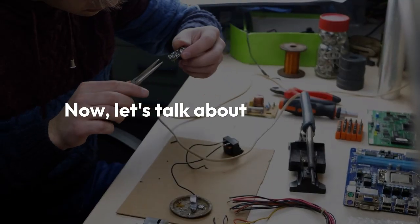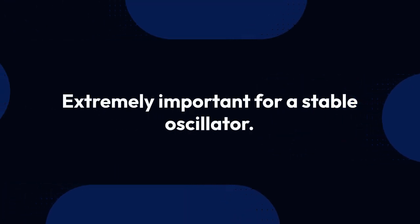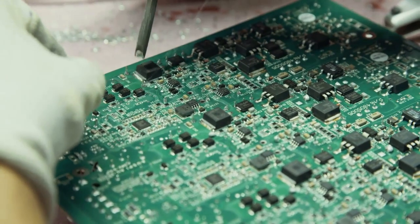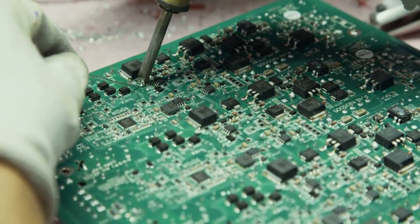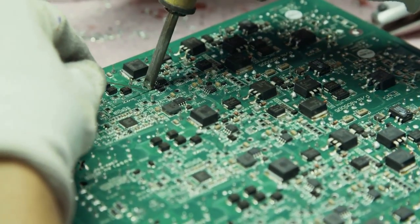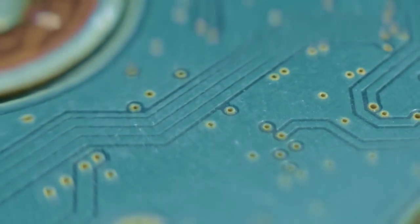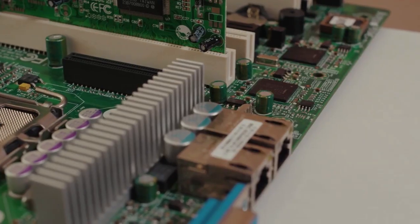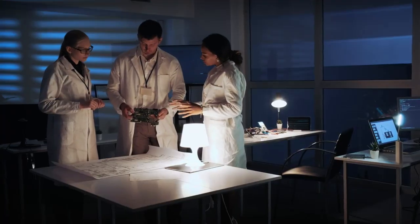Now, let's talk about PCB layout. This step is extremely important for a stable oscillator. Place the crystal and its two load capacitors as close as possible to the STM32F4's OSC_IN and OSC_OUT pins. Keep all traces connecting these components very short and direct. This minimizes unwanted inductance and capacitance. It also reduces noise pickup.